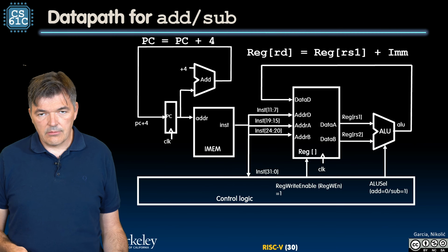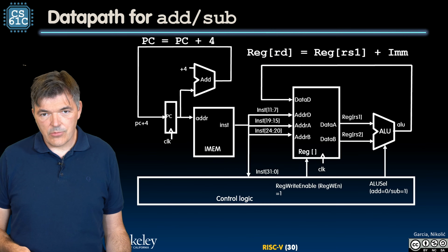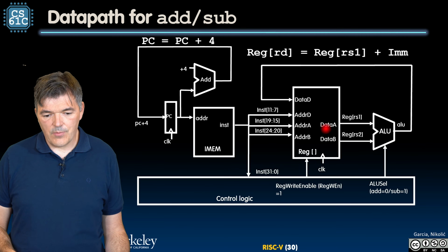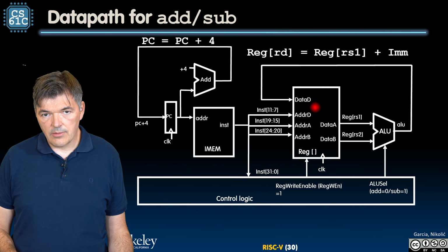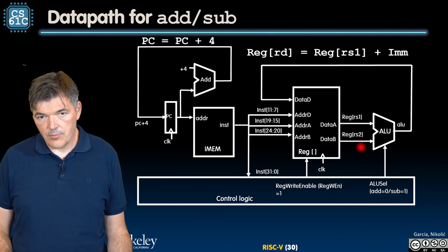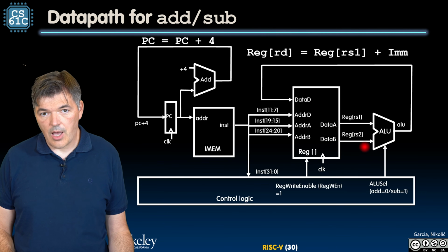We got 2/3 of what we need here. We got the value from RS1 in the right place in the ALU, and we are writing it into the correct place in the register file, except that at the second input of the ALU, what we would call the B input, we have RS2 connected instead of the immediate.